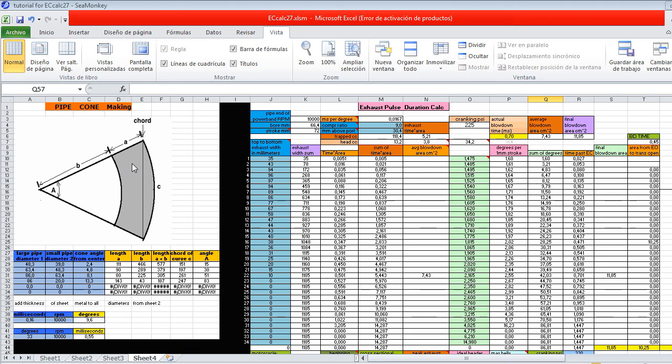So then when using the ruler, measuring for 151 millimeters from here to over here, if you got that curve extended out here, you would just move it around till you find where it crosses at 151. Make that mark and draw the line back to the pivot point. So then this section right here will be the pattern for your cone, which if you cut that out with scissors and you place that on top of the sheet metal, then you can outline it with a felt tip marker and then cut out the sheet metal.